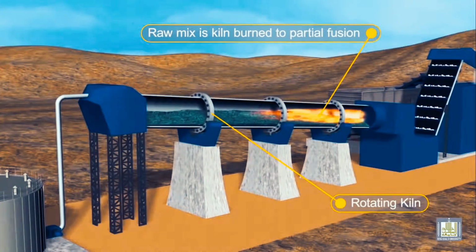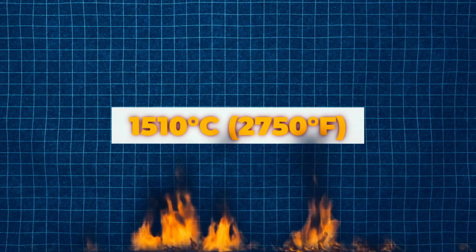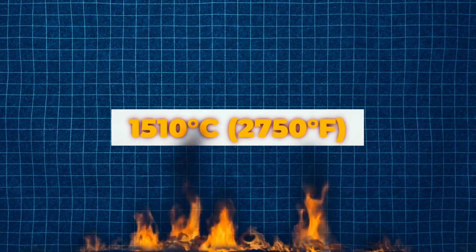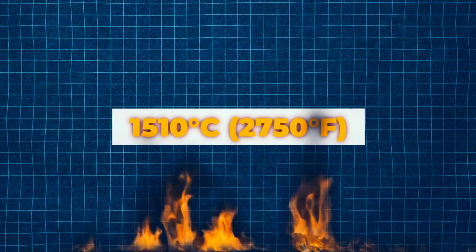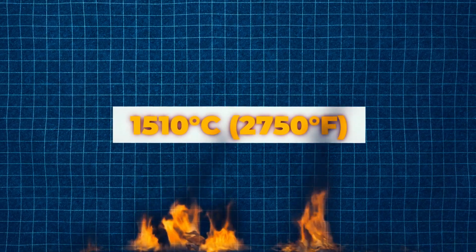Dehydration and formation of oxides of silicon, aluminum, and iron, 900 degrees Celsius, 1650 degrees Fahrenheit, to 982 degrees Celsius, 1800 degrees Fahrenheit. CO2 is evolved and CaO is produced through calcination, 1510 degrees Celsius, 2750 degrees Fahrenheit.